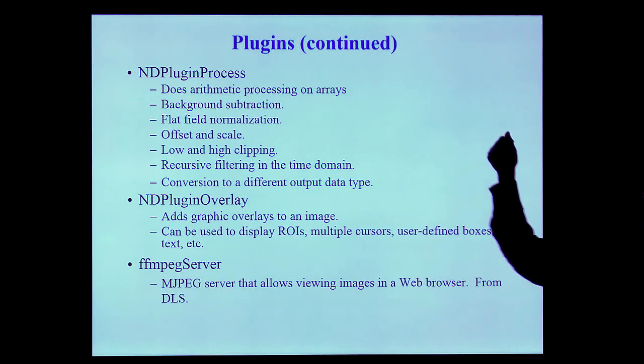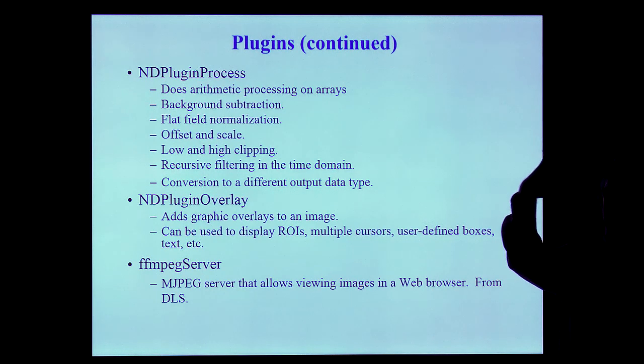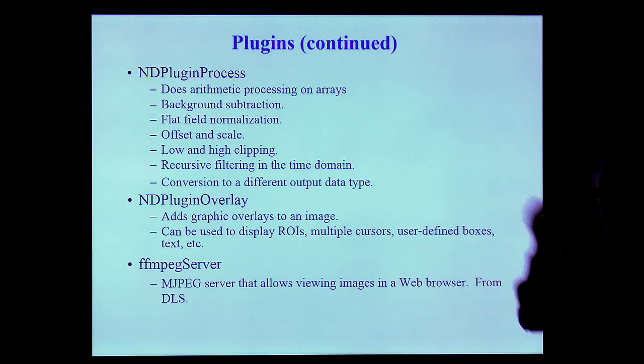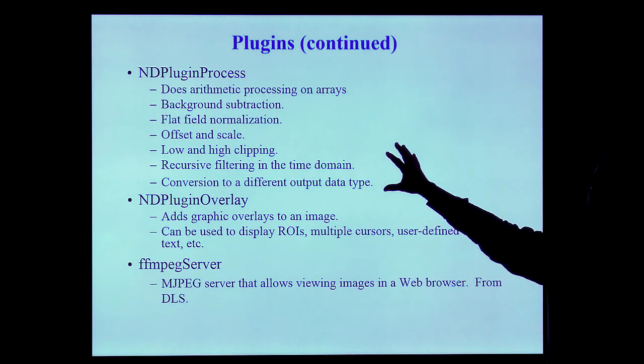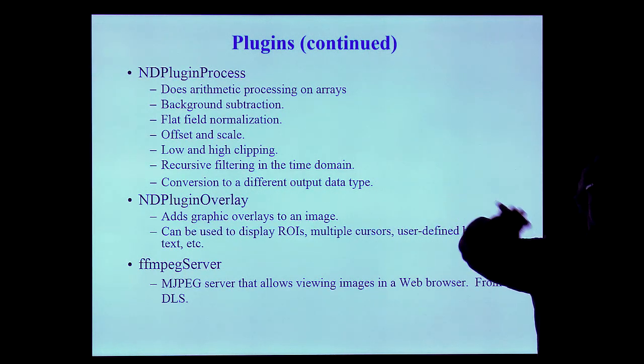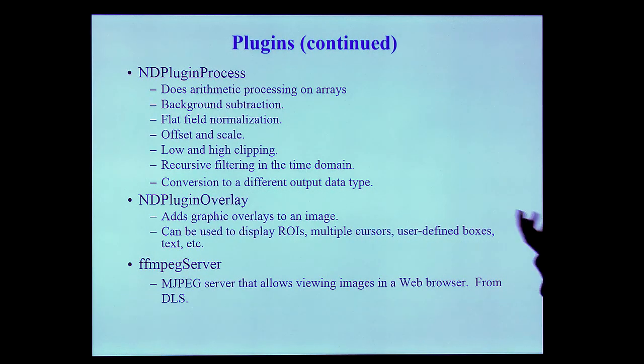I set that up so that the first 4 would be getting their data from the 4 regions of interest, and the 5th one is set up to get it from the whole detector. But that's reconfigurable at runtime too. That was just a decision that was made. You would also have to change your screens, right? Because right now the related displays only call up 4 regions of interest, not 6. But if you write your own screen, then there's no limit.